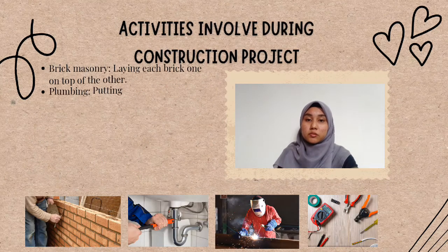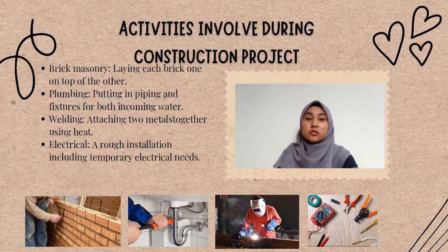Five is about brick masonry. Bricks have been used in construction for decades and are still used often today as a highly efficient material. Brick masons lay the bricks, ensuring that they are laid in a way that is structurally sound. For example, laying each brick one on top of the other allows cracks to go all along the entire wall. If the bricks are offset, as you will often see, it makes severe cracking of the mortar less likely.